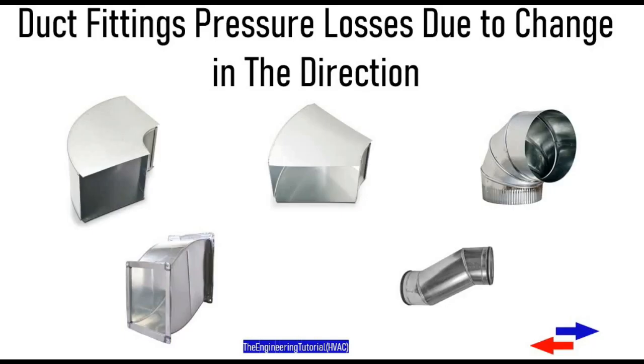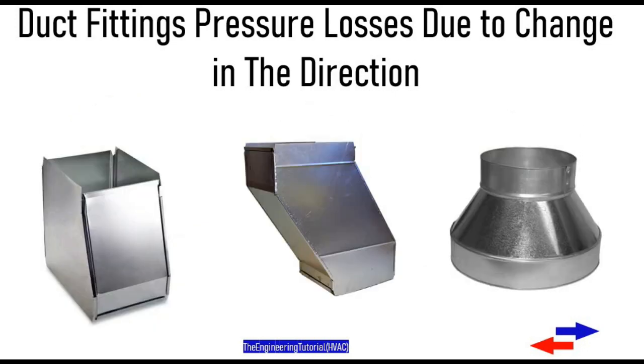Additional resistance to airflow occurs anytime the air flows through a passage that is not straight or has a change in cross-sectional area. For example, the air has to flow through a 90-degree elbow or even a 45-degree elbow, offsets or reducers, so there is additional resistance in that fitting.